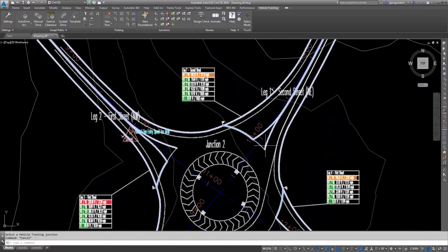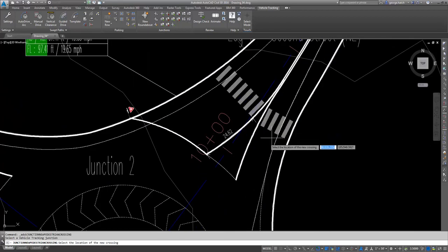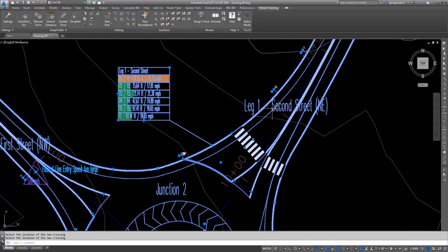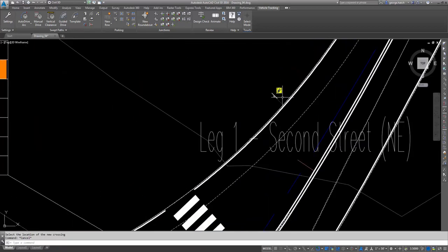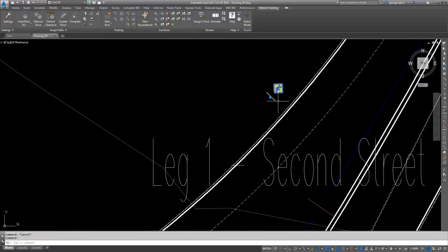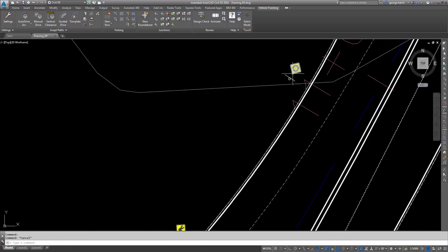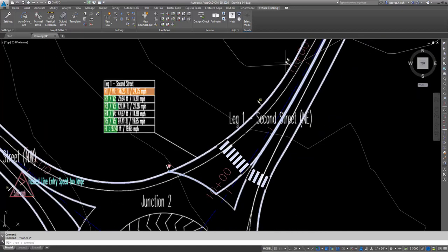And you can see here that there's a couple of other options. Up in our dialog box for junctions, we can add new roads, which would add a leg. We can add splitter islands. We can do things like crosswalks. Maybe I want to add a crosswalk about this location here. Now, what's interesting about the crosswalk that I just added, not just does it graphically add your crosswalk, but it also changed our signage. You see here that we have a sign that specifically signals a crosswalk, and our roundabout or rotary, if you're from the Northeast, signage has actually been moved up.